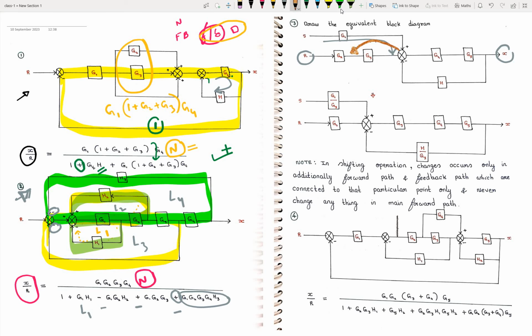See here, this is the additional signal added. When you move from input to output, what we have here is G1, G4, G5. When you move this summing point here, the resultant should be the same. G1, G4, G5. So I have shifted this incoming signal from here to here. Now the resultant is, just forget about it, G3. Say we have only G1, so G1, G3, G4, G5.